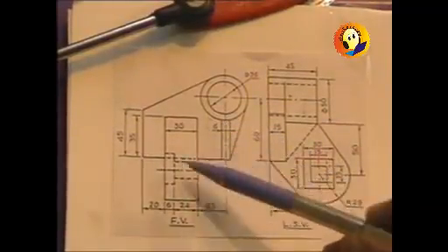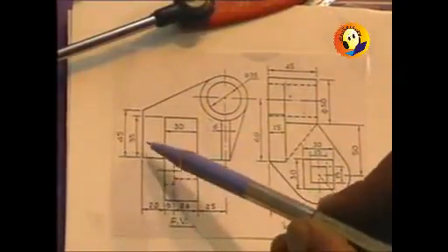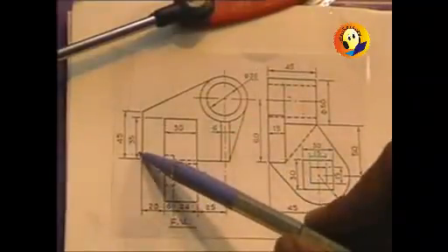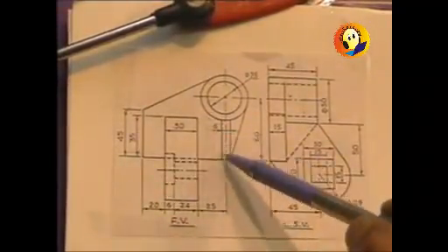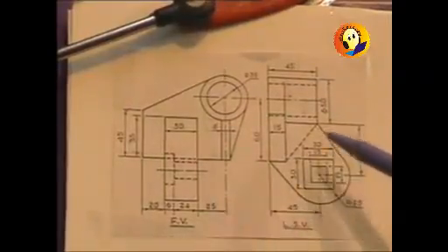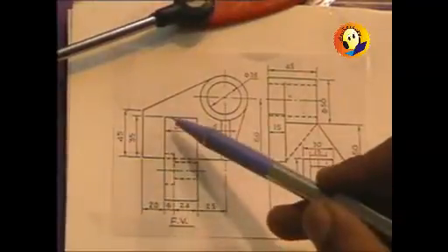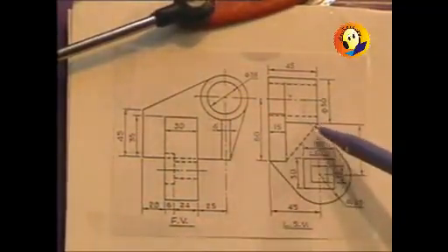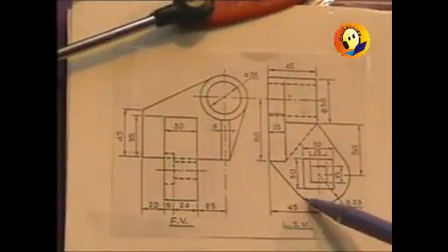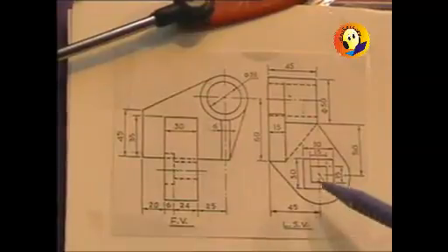And why is it dotted? Because of this portion, because we are going to look from the left hand side direction, and this particular portion is in between that rib and the direction of viewing. Ultimately this will not be visible, and so it is becoming dotted. Then we have this particular portion corresponding to this part which is shown here. We have a projection which is coming like this, going till this point, which has some circular part, and these lines are actually tangent to it.